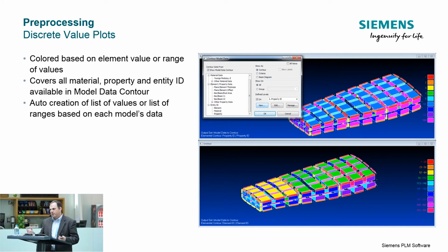If you have 100 different thicknesses in your model, we will create a thickness to color relationship, and then that single color will be associated with elements of that particular thickness. The other option would be to assign a color to just a range of thickness.